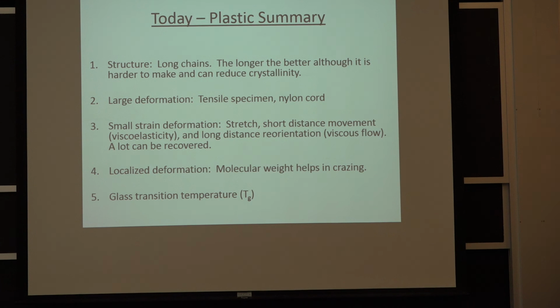And thank you so much for the questions, by the way, because I know I can be a little jumpy sometimes. I try not to, but anything that wasn't clear, I want you to remember only 2 or 3 things, right? Spherulites, molecular weight, and I guess you have different mechanisms of failure. You can have crazes, shear banding, or just regular deformation. And that's always the funny thing.